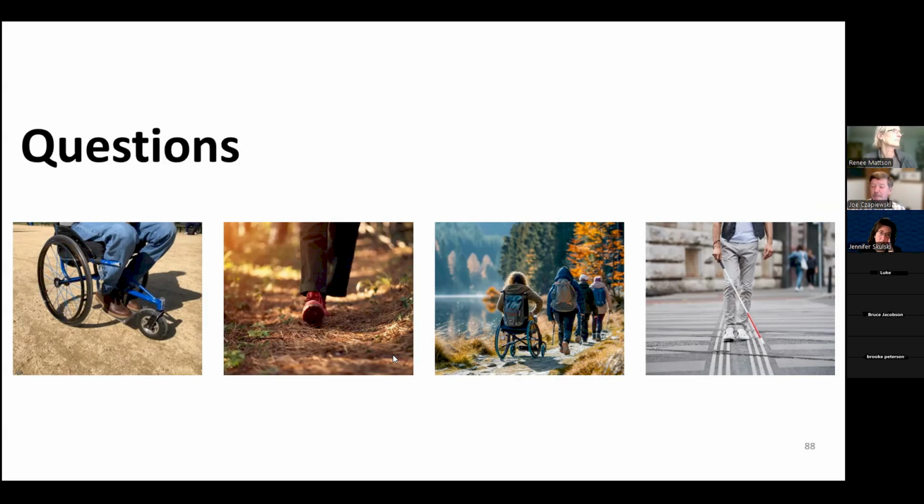Right, that's a great question. They need to have the accessible route that connects the site arrival point to the entry of the playground. Where we see the surface has been applied above grade and hasn't been excavated for a subgrade, that's where we see the majority of issues, where they're using maybe a plastic timber border with a plastic molded ramp. Over time, what we've found in our accessibility assessments is that those ramps get so hot that they end up melting or warping, and so they're no longer compliant.